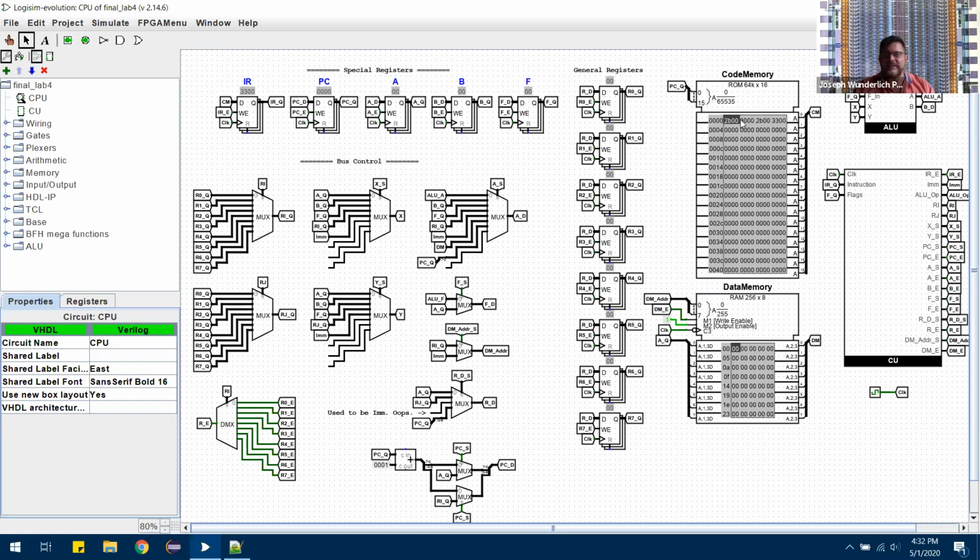Now, it was interesting. If you're not familiar with assembly language that much, what you'll notice here in the computer is that this thing is moving along. For a second, it pops down to this next line. The reason that's happening is because directly after the fetch phase of the instruction cycle executes, it is immediately incrementing the program counter. So it goes to the next one immediately, it's just part of that phase. But then because that last instruction tells it to change the program counter, it gets changed again. And so that sets it back to this first instruction here.